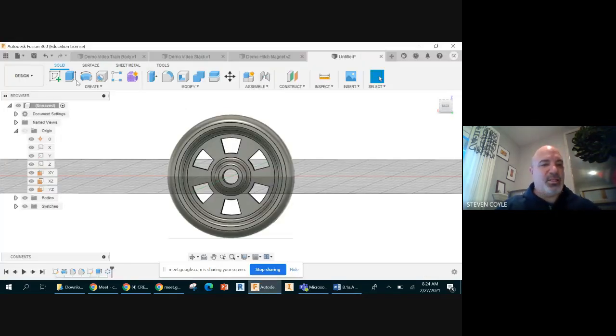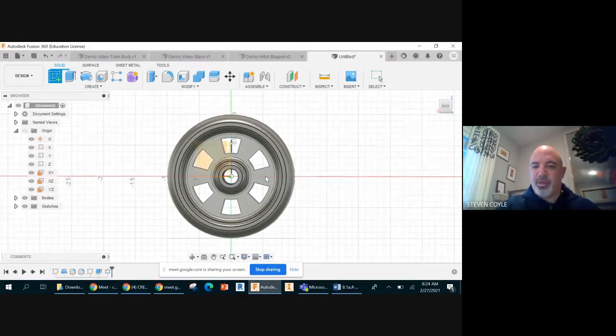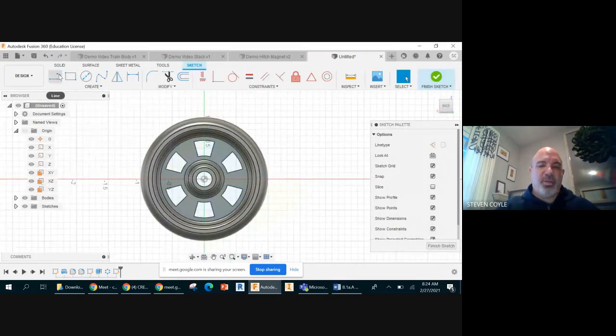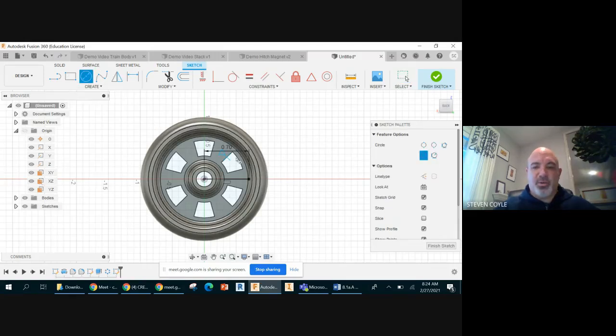So let's take a look. We're going to start our sketch, and we want to select the face that those cutouts are drawn on. A shortcut you can do, if I wanted to figure out where to put that circle, is I could always just draw a line out 0.7 and delete it later. So I go 0.7, that's going to put my linkage peg out here. Now I can just draw out my dimension. It was 0.25.